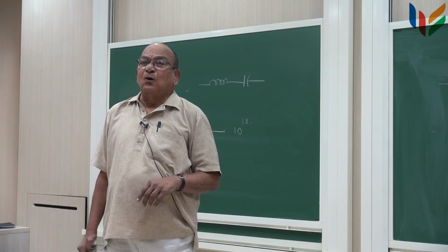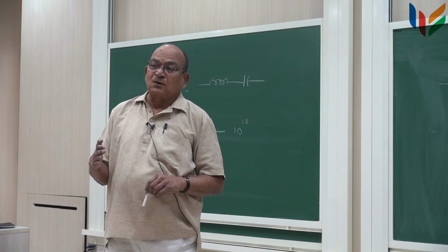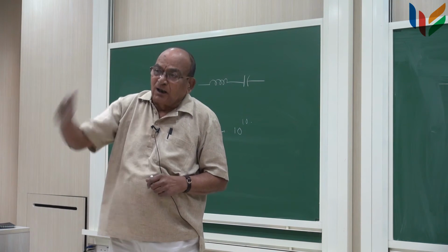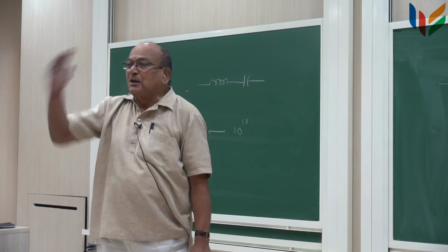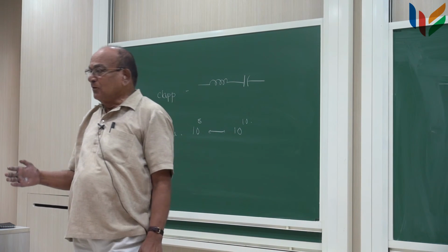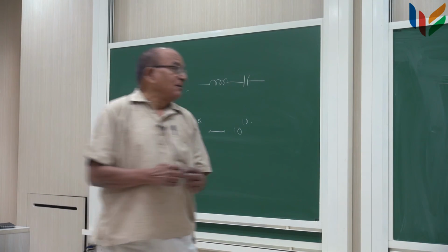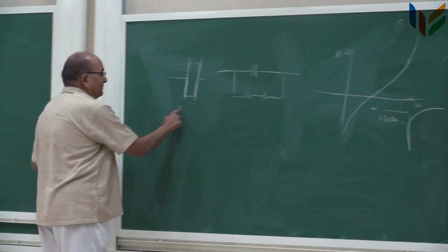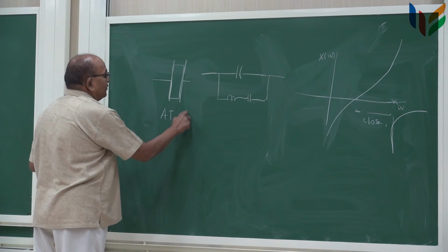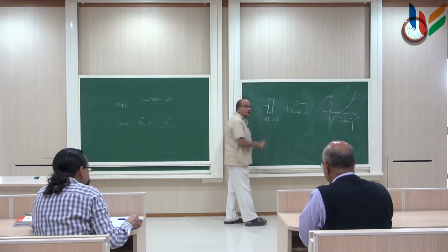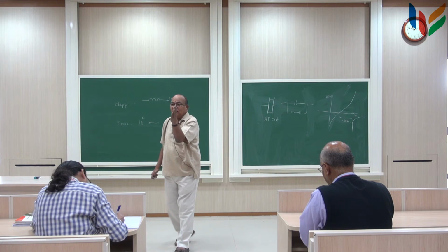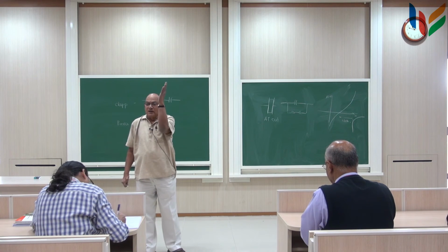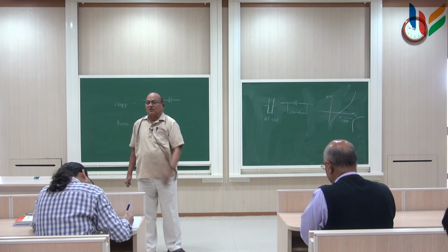And it also has been found that if you cut the quartz crystal in a certain crystal axis in a certain way, the frequency stability is even higher, and this cut is known as the AT cut. I don't know what this AT stands for. It is some angle with respect to the crystal axis, and that angle is called the AT angle.